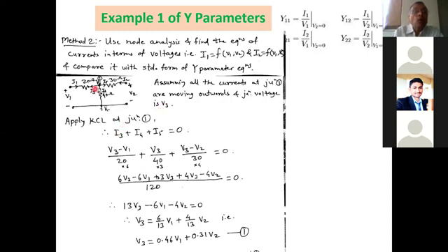Okay. So for this junction, I have assumed the voltage as V3. V3 is the voltage at this junction, and what we have to assume in node analysis is that all the currents are going outward from the junction, right? So I3 is moving outward, I4 is moving outward, and I5 is moving outward. I have purposely left the symbols V1, V2, I1 and I2. So currents are starting from I3, I4 and I5, and voltage is V3.